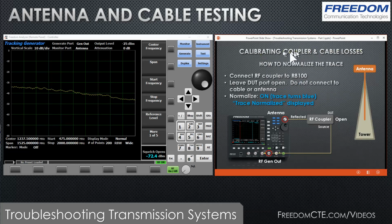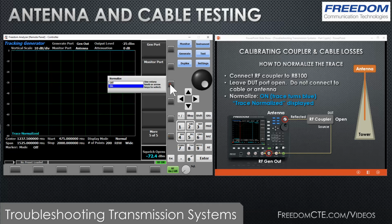Once we have those set, the next step is to calibrate out the losses in the RF coupler or return loss bridge and the test cables. The way we do this is we hook up the coupler as indicated here. We also have a great app note on the website, and then we leave the device under test port open, and I will do that. I have that all set up right now, and I'm going to go to the last screen, press normalize and on.